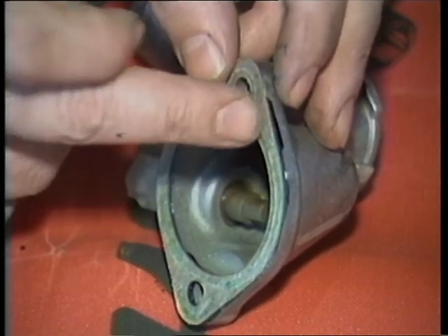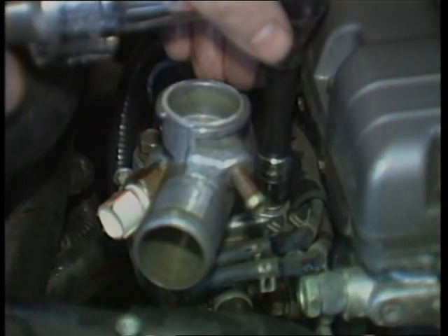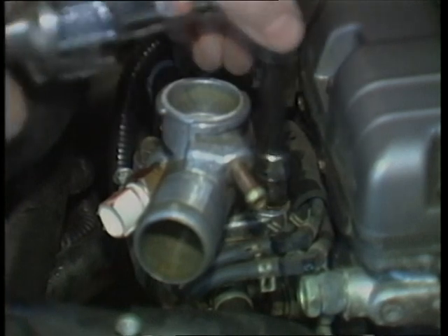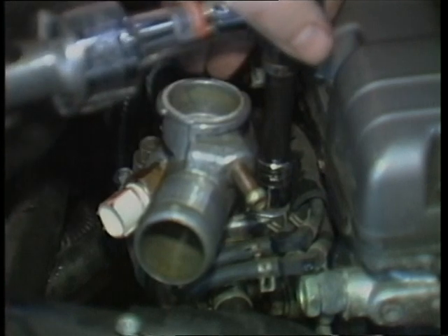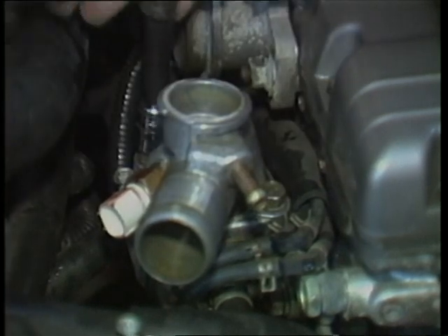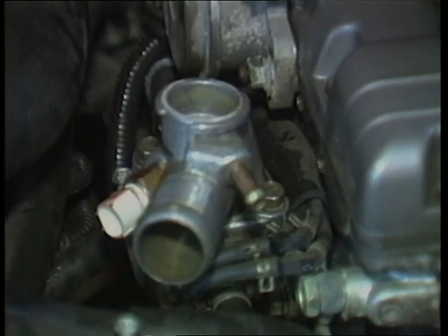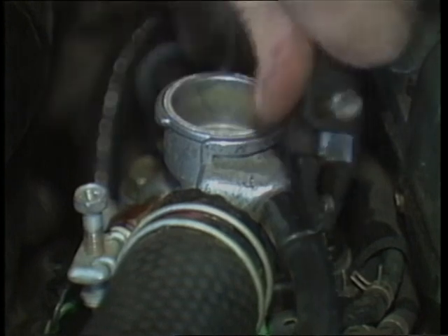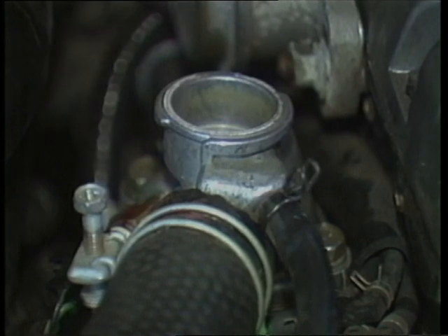Assemble the parts, and then tighten the bolts down a little bit at a time. A common mistake is to over-tighten the thermostat housing bolts. This will warp or crack off the ears of the housing. Just snug them down. Then install the hoses back onto the housing. Make sure the clamps are positioned properly over the fittings and tighten down the screws securely. You may want to pressure test the system after repairs.